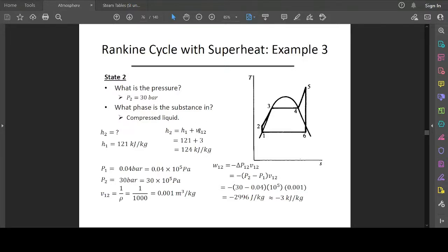Then you find the corresponding temperature for the average pressure you've calculated, and that will be the saturation pressure. Then you find the corresponding temperature. Based on that, you can go to the steam table and read out the density of liquid water at that temperature. Okay, that's if you want to be specific. Whatever density it gives you, if you take the inverse of that density, that will give you the specific volume. But in this case, you can make a clear assumption to say that the density of water is 1000.